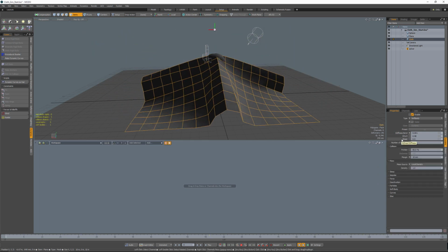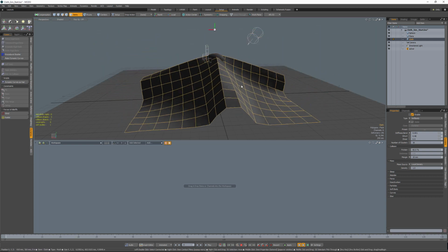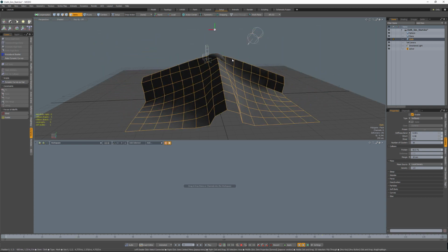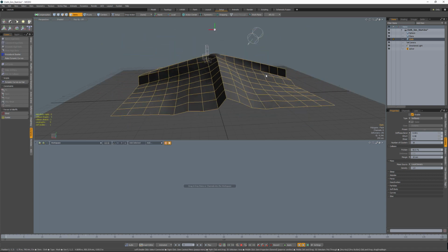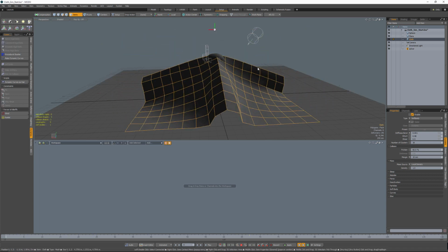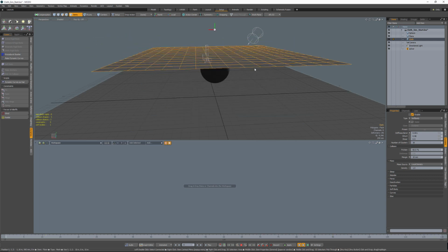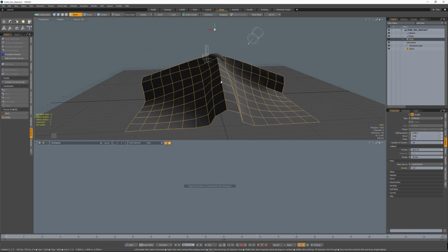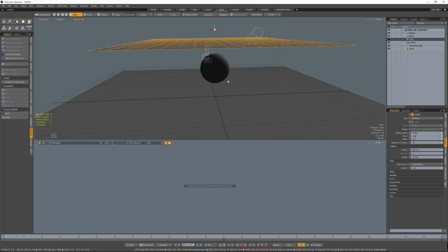Okay, so moving on. The stiffness bend is, like I said, your overall bendiness of the actual material. Now, struct and shear are very similar things, flip sides of the same coin. These are going to be how the overall shape is allowed to give and flex. Struct covers the give and flex along edges, so along the actual edges of polygons, this allows bendiness. You can see we've got a relatively straight line through there, and that is caused by the struct. Shear, on the other hand, is how each individual polygon bends within itself.